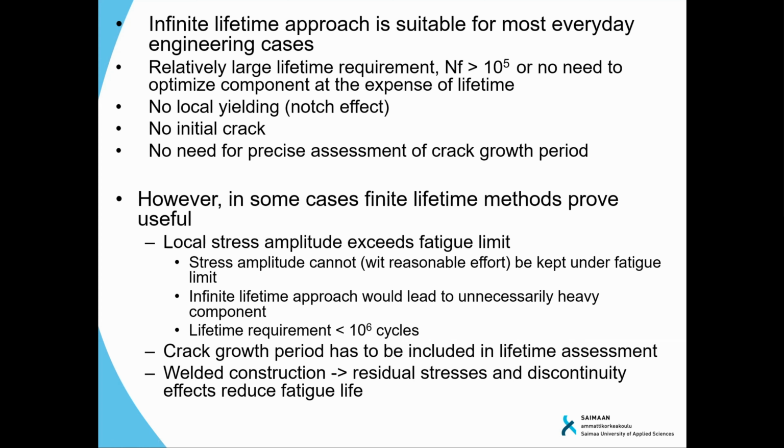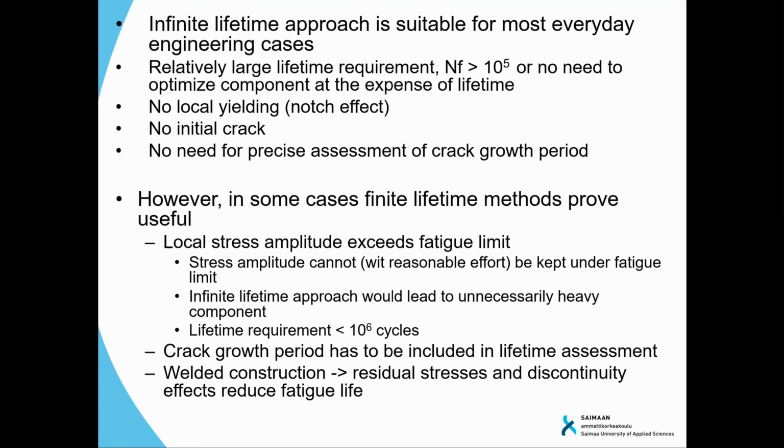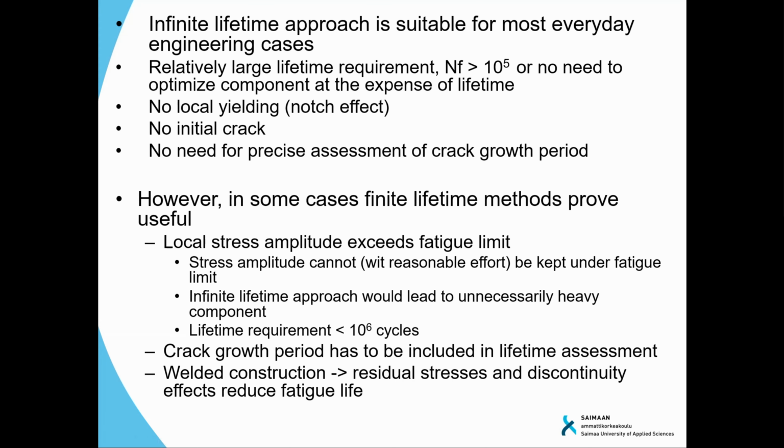If we have found that in some component there is already a fatigue crack that has initiated, then our calculation method doesn't give any reliable results because the crack is already propagating, and the infinite lifetime method is based on the assumption that we can prevent the initiation, so that initiation will never happen. That is the base idea behind the infinite lifetime. And if there already is a crack initiated, then we are already outside of the game area of the infinite lifetime method.